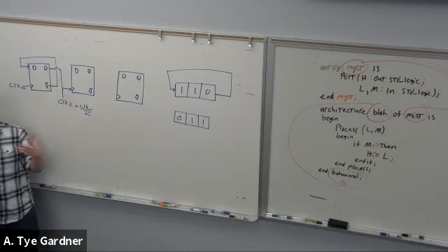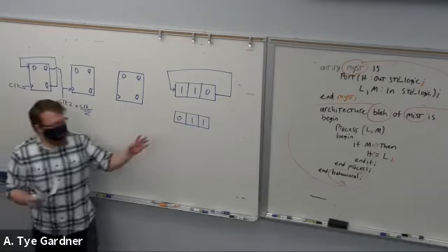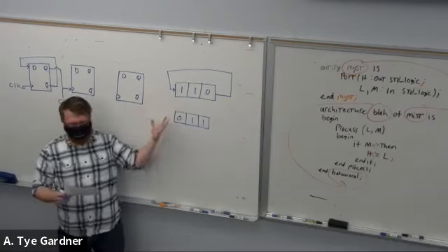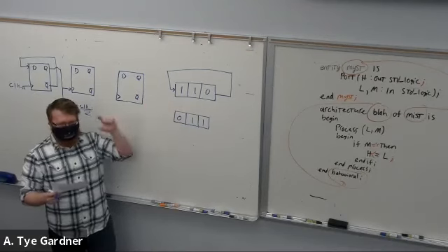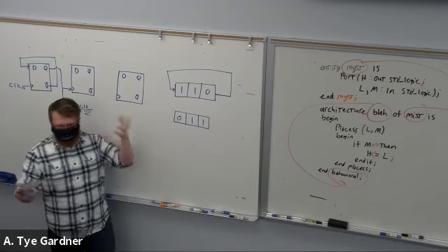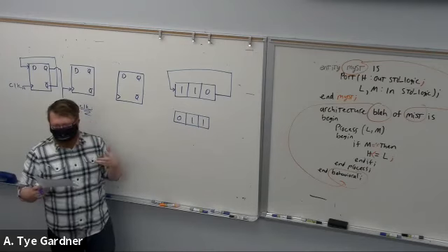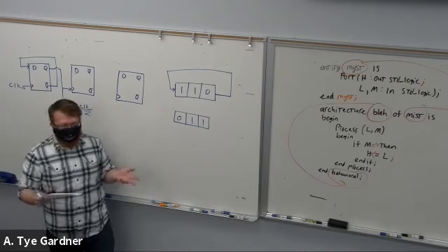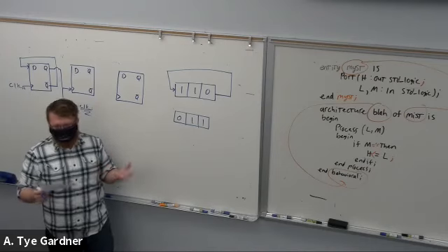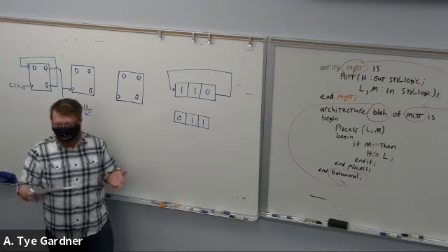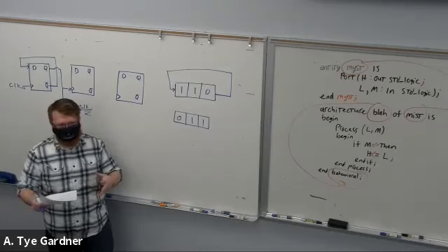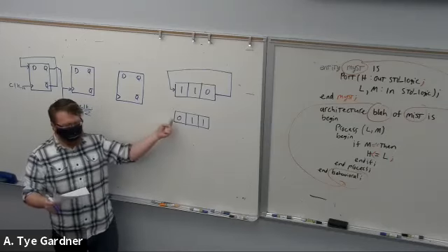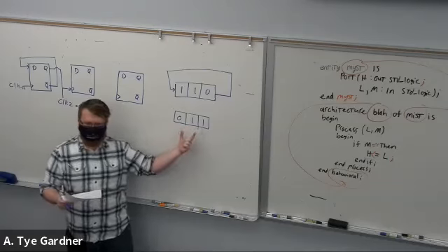I would probably do a 4-bit shift register and draw the circuits out with the AND gates and stuff to make it fully synchronous. Then I could say, if you have a 50 microsecond clock to Q delay and a clock of 5 kilohertz, what is the value at 1 millisecond? So 1 millisecond after we start, what is the value of the shift register?